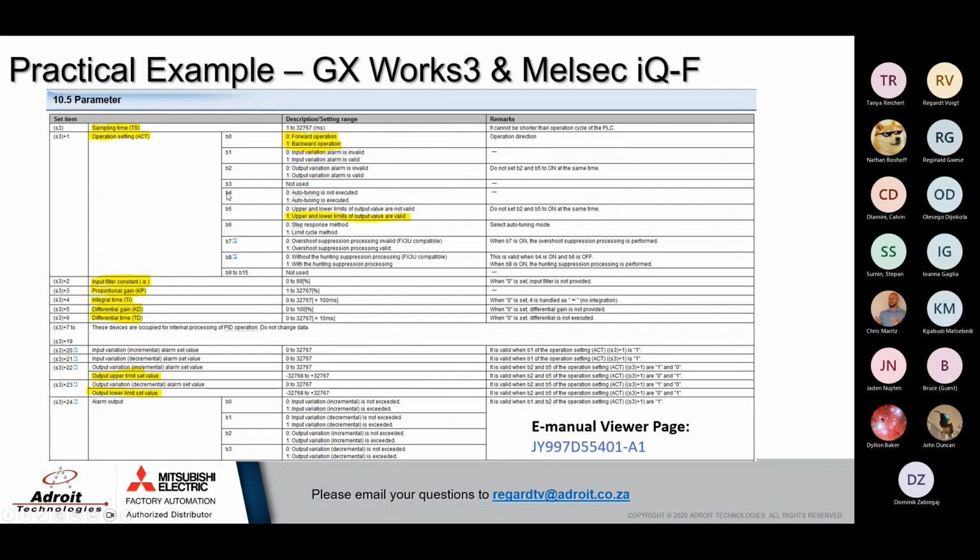This B4 there. Then you can use that to instruct the PLC to find an optimal control system for the quickest stabilization. Okay, that is if you use a Mitsubishi iQ-R PLC. If you use another vendor, I suppose they will probably have an auto-tuning capability as well. If not, then you're going to have to use a manual tuning method.